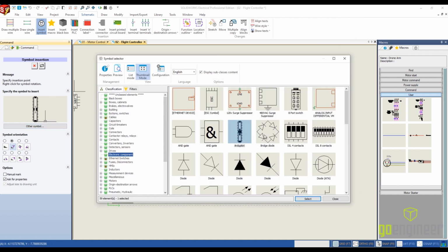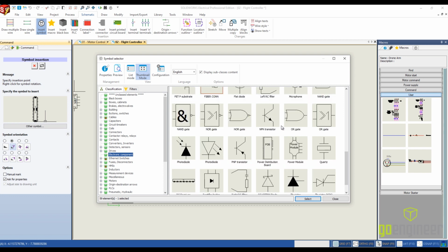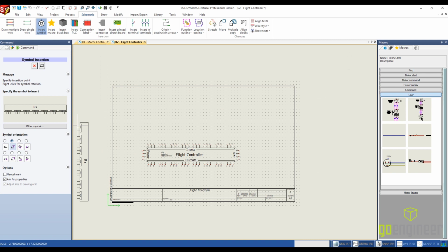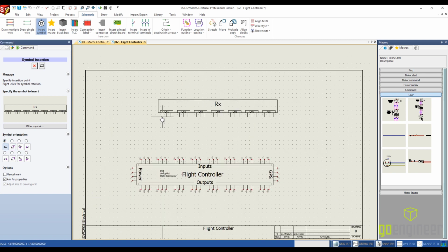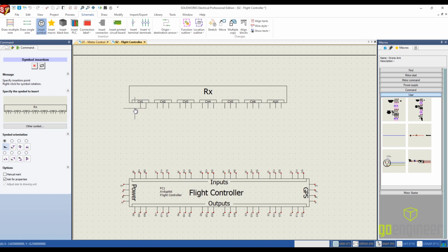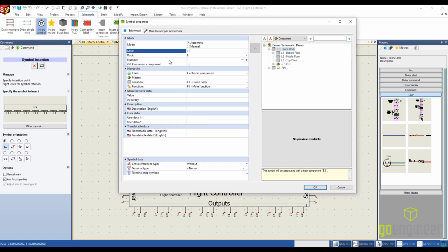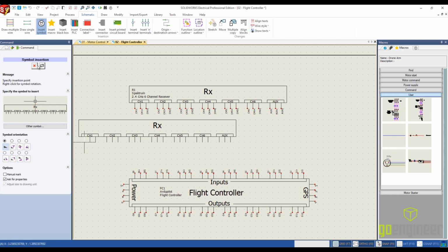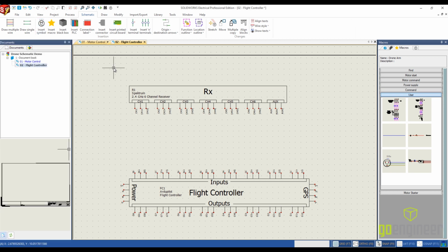And then next, we're going to put in the RC receiver. So I can grab that symbol, orient that the right way, and we can drop this into place. And I'm going to leave a lot of room here because with some of these wires we get a lot of crossing going on. So I'm just going to leave myself some room. So there, I'll give it a name. Again, the manufacturer part is already assigned because I've done that in the symbol. So there we've got that.